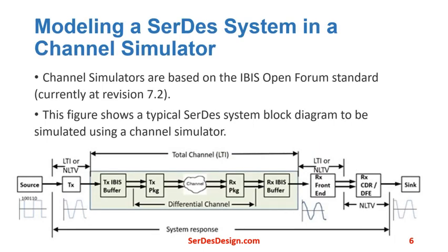So let's talk about modeling SerDes systems in the channel simulators. Channel simulators are based on the IBIS Open Forum standard, currently at revision 7.2. This figure shows a typical SerDes system block diagram to be simulated using a channel simulator. The block diagram is generic for any channel simulator, but each tool has its specific way to represent this block diagram.